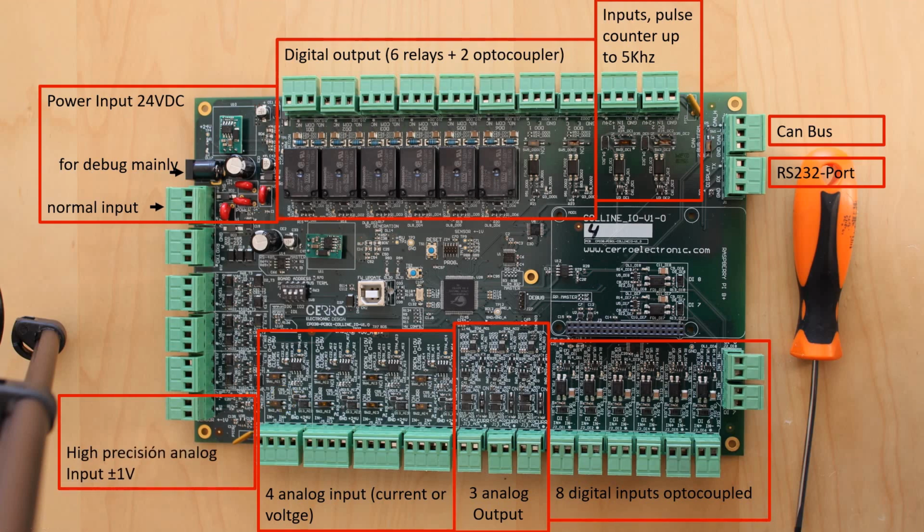This input is for a high precision analog sensor. This is the area for the PT100 temperature sensor input, and this is the main communication port of the board based on RS485.